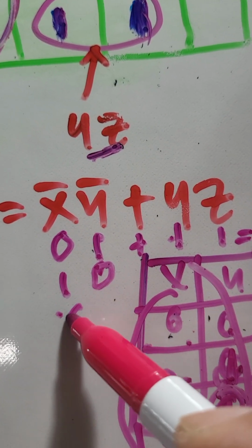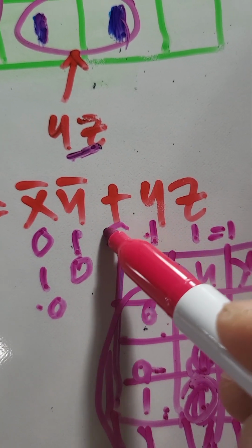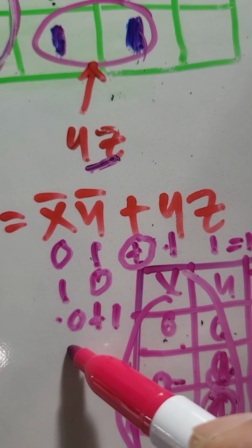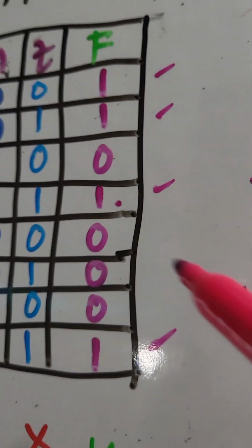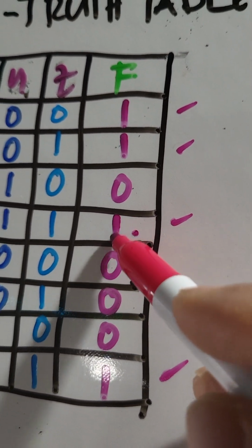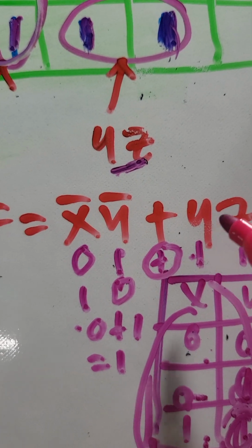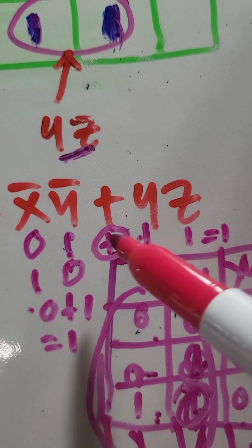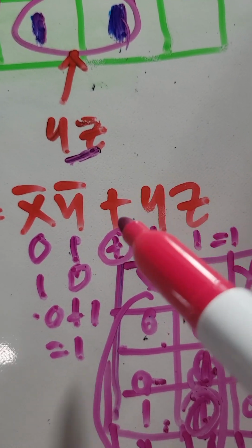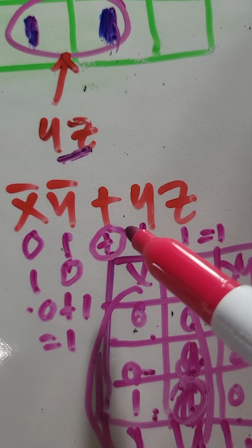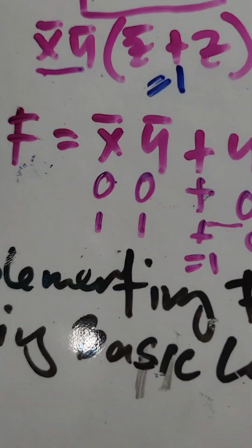And here on the other side is 0. But this is a plus sign. Okay, so this is 0 plus 1. That is equal to 1. So correct. Right? Our output here is 1. So this function that we got in our Karnaugh map method is also correct. We prove also that the simplified output is correct. Same also here.